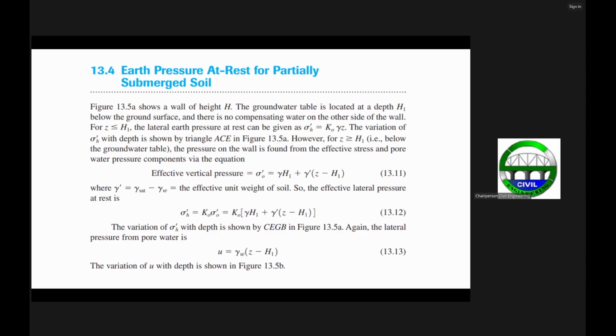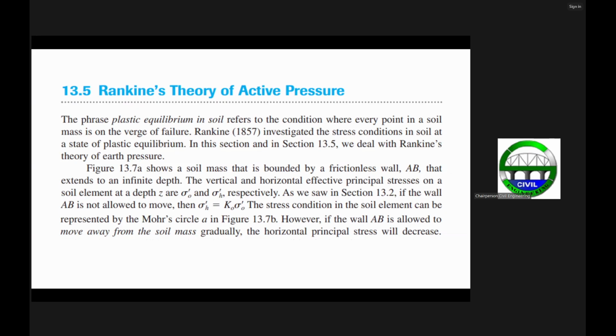So far we have discussed retaining walls wherein the wall will not move. Now, in practice, we normally consider wall movement. That is why in practice we normally provide the active earth pressure coefficients as well as the passive earth pressure coefficients in the geotechnical report.